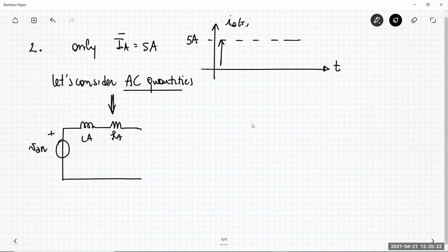The back EMF is constant, you are in a steady state, so this is a DC quantity, and for our purposes here, we want to consider just the AC contribution. So the back EMF is null. This is the voltage A, this is the node A, this is the node N. This is the circuit I have to consider.